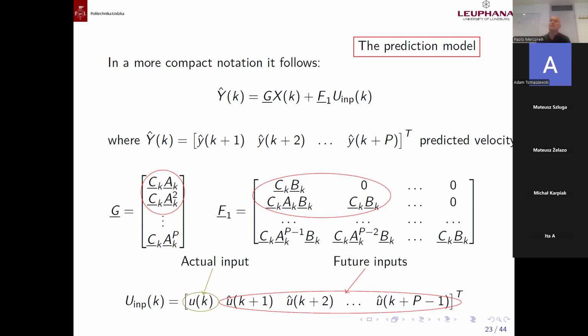Even though the disturbance is not so critical because of the presence of the feedback, this fundamental MPC structure can achieve our goal under some condition, or under some approximation. The idea is to calculate this U vector, and of course at each step we apply the actual input, and then we recalculate at each time.